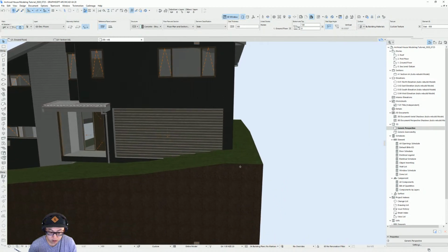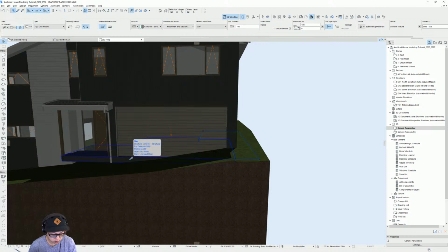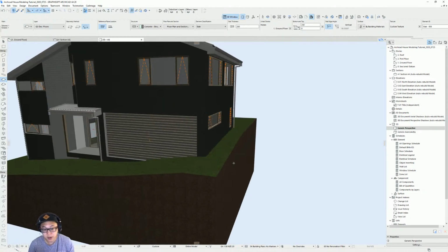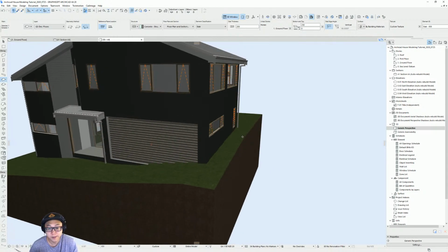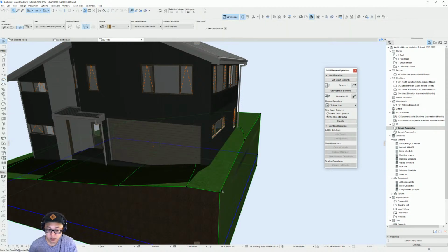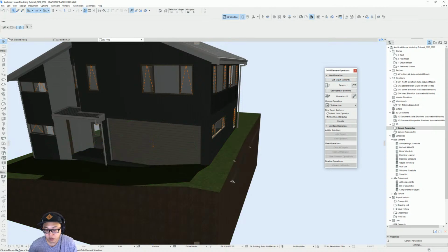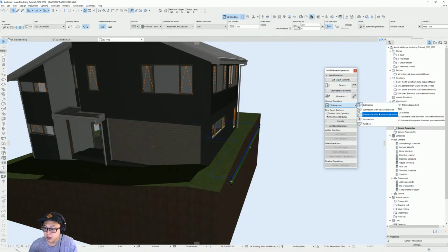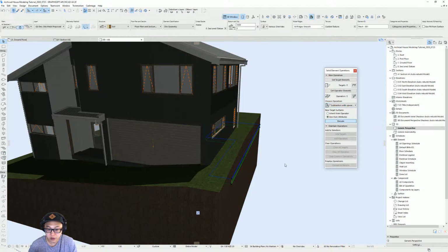And maybe I'm just going to select Alt and hover that slab here. And I'm just going to try to mouse over the slab that I just created and press Ctrl Alt to inject the same properties so they'll also be on the same height. And now we can do a solid operation. I did show you that earlier for, I think, the staircase. It's the same thing. I'm gonna use that as the target. The thing that I want to edit is the mesh, and what I'm gonna use to edit is the slab here. Subtraction with upward extrusion. Press OK.